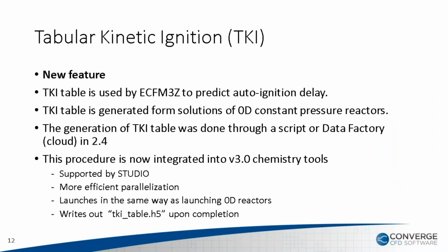And for the tabulated kinetics, for the table generation, we actually use the 0D constant pressure reactor to generate a TKI table. The TKI table is a tabulated kinetic ignition table. This is used by ECFM to predict auto ignition delay.